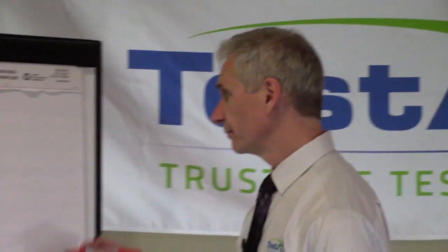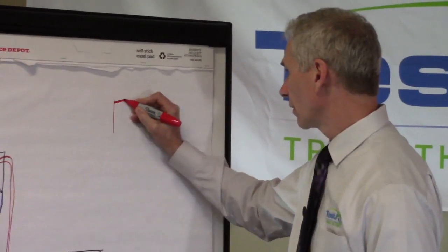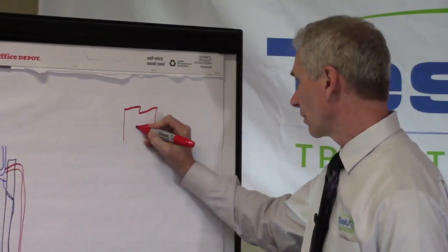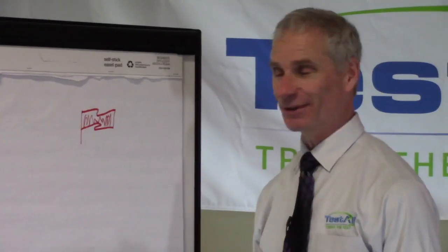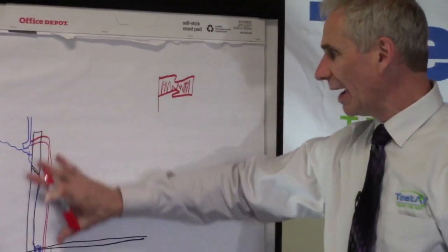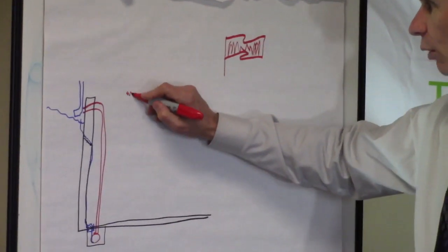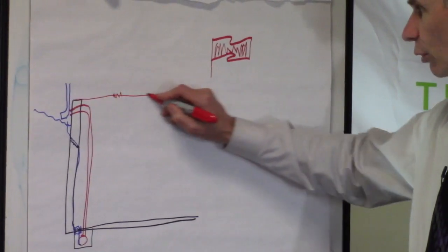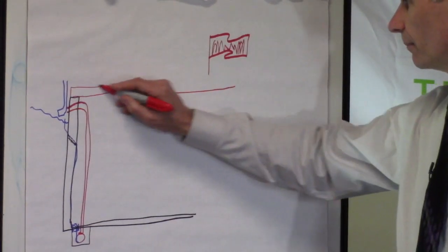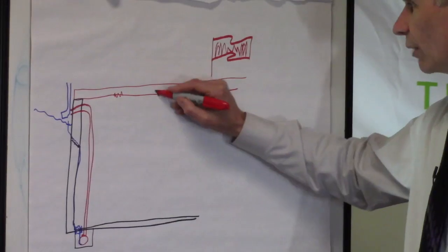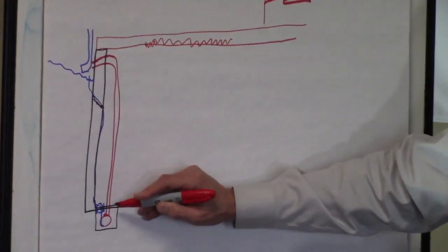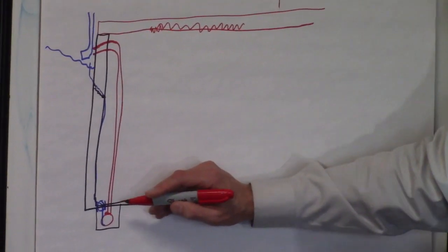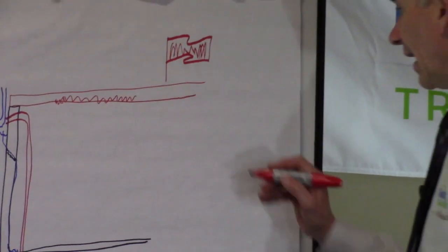So in these standards that I've been talking about, the limited, the screening, the survey, I've talked about red flags. Let's take a look at what red flags are. That's a red flag, right? But that's not really what we're looking for. A red flag would be if you have an area of the home where mold is landing. So if you have your floor joists that come out and you have mold growing on that floor joist, that's a red flag. If you have water stains in the basement, that's a red flag.